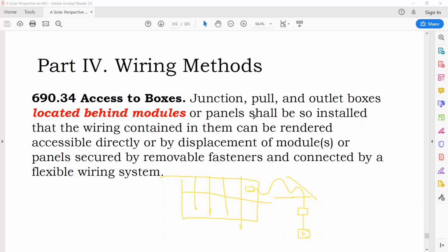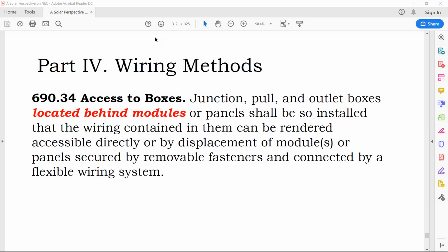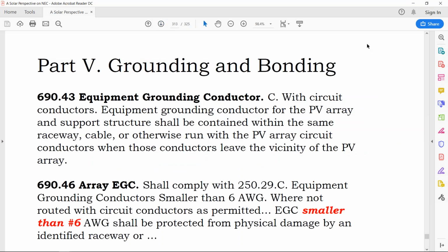And the reason why I do that is up on the rooftop, you don't have any exposed wiring or conduit because we're going into the attic right then and there. It makes the array look like it's magically hovering above the rooftop and gives you a really good, clean aesthetic, which I think is critical to maintaining the long-term value of the system.